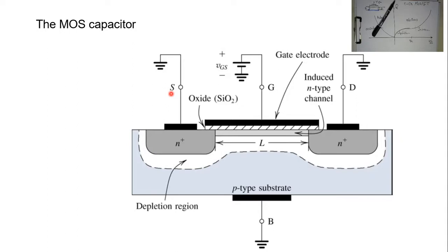We have to first agree that a capacitance usually has the same look: a dielectric, an insulating layer in between two conducting or semiconducting materials. So whenever you have a format in this manner, then you have a capacitance. And let's see, do we have such a format in our MOSFETs? Okay, so first of all, before going into details, we have a very good sign that we have a capacitance, which is this dielectric material.